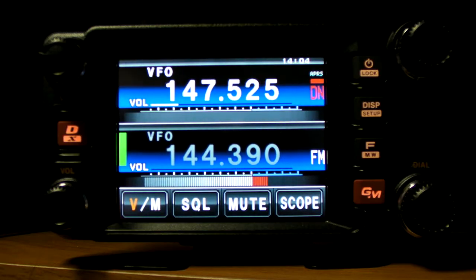The reason I'm using a different frequency than, say, the national simplex calling frequency is, I really don't think that people are going to want to hear that kind of data noise in the background. So I'm all in favor of looking for a national simplex frequency for the digital voice here. And I've seen 147.525 being proposed on other sites.